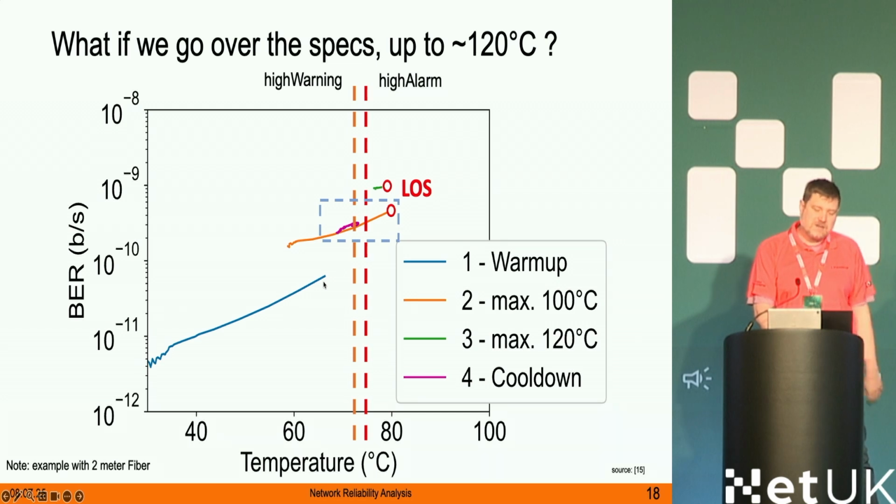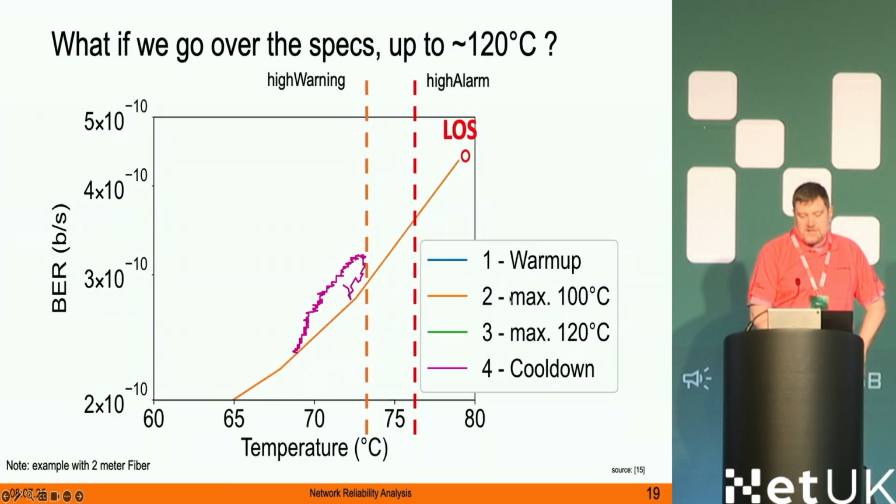It was quite interesting because for the first warm-up, I put a limit. In our software, we have an integrated limit of 65 degrees. We find this quite high. When it doesn't go down, we usually shut down the software. So I just wanted to see what curve we have here. And then I removed the limit up to 100 degrees. So I was looking around what would happen. And around 80 degrees, it started to stop. It reported a loss of signal.